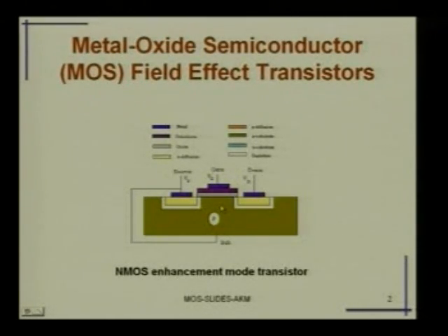Normally, you will see that we talk about micron technologies today. Essentially, it says what the length of the channel itself is. If the channel length is less than a micron, then we are in the submicron technology. Today, you will find that we have 0.18 micron or 0.45, it slowly went down. Initially, it was about 5 micron, then 2 micron, and the technology is slowly shrinking. The idea here is to shrink this channel as much as possible. There are certain consequences of it, we will see that later.